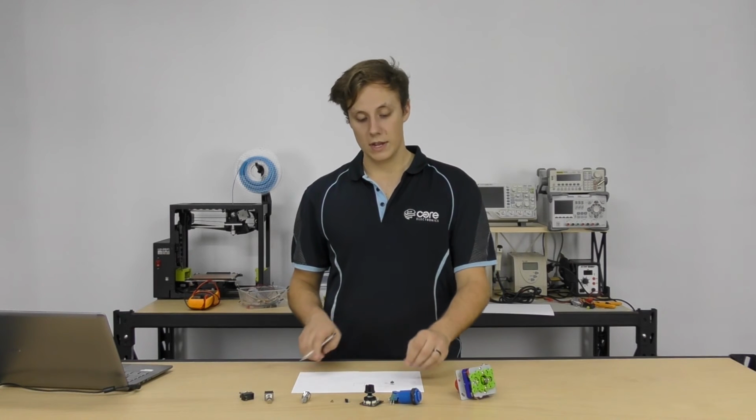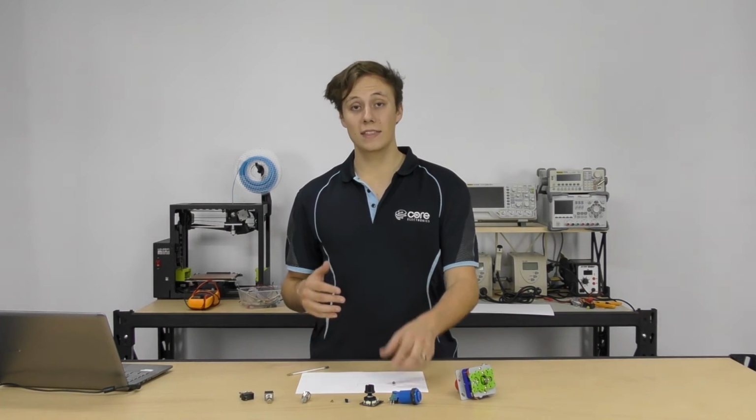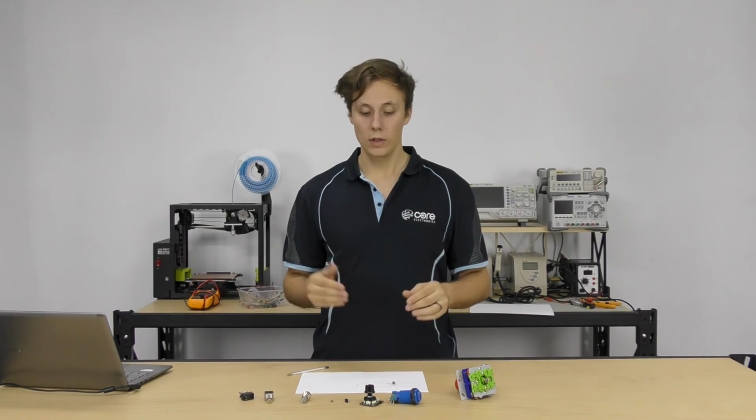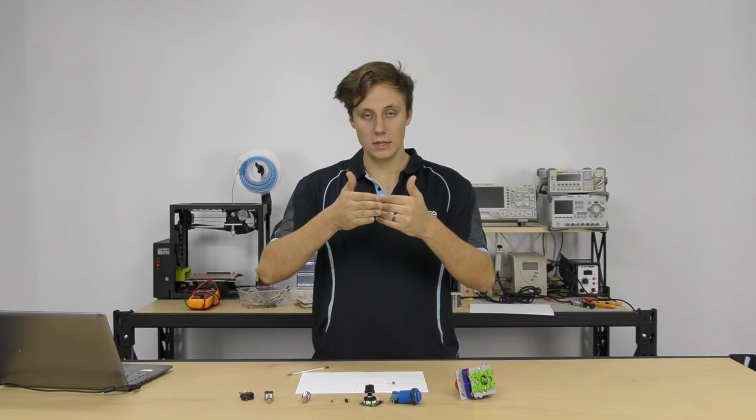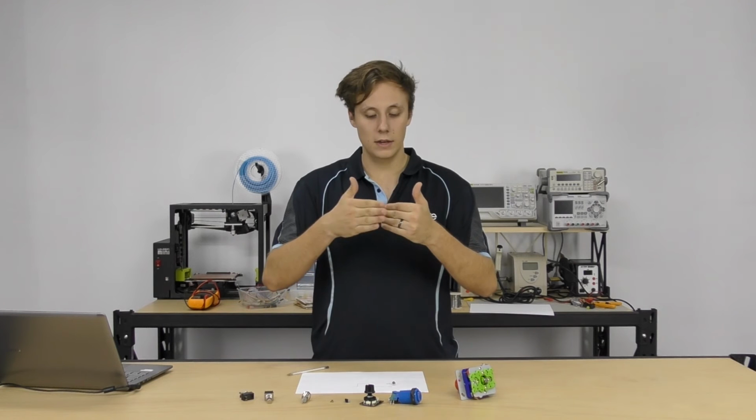But the important thing to note is that inside every switch, there are mechanical contacts which have to make contact in order to allow electricity to conduct. And like anything mechanical, those contacts have momentum, a velocity and a mass behind them. So they're going to actually bounce, because when they hit, they're not just going to sit and stick. They'll hit, connect, and bounce, and then finally settle.